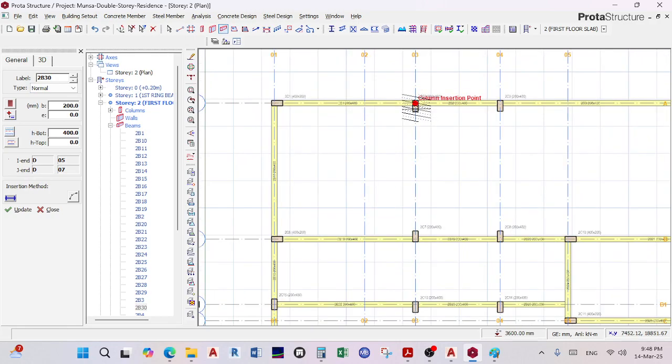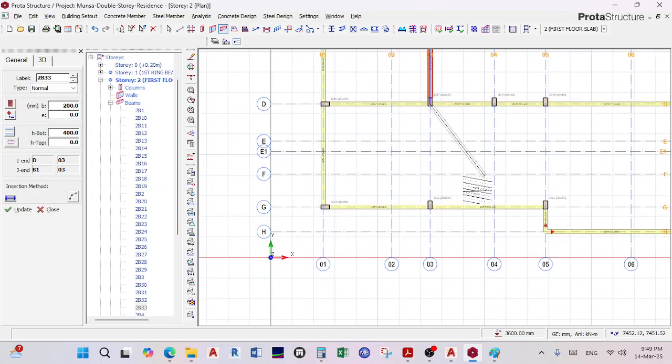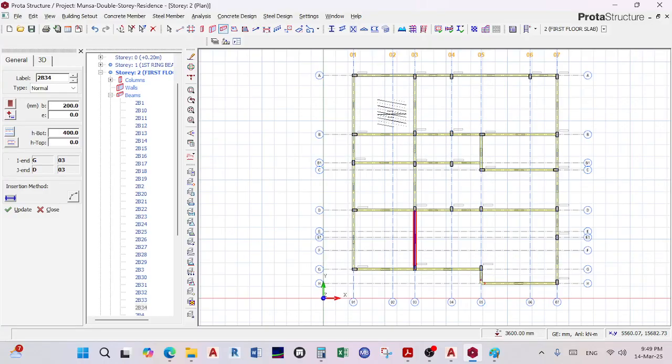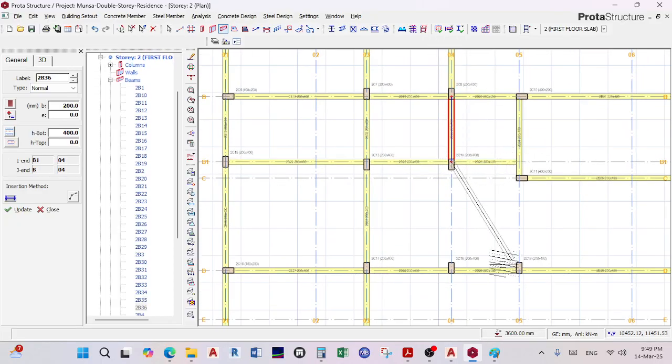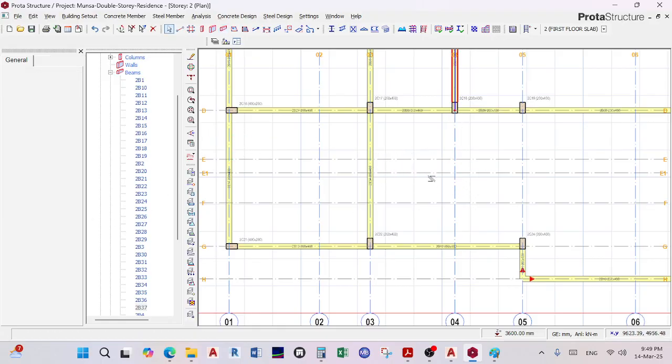For example, this is the first floor right here. There to there to there to there, and then there. So now I've created pockets for my slab. Here you can put your rebar there and there and there and there. So I'm creating those yield lines like that, there, there. Do I want it to anchor there? I do not. But let me just come out of this command, Control S.